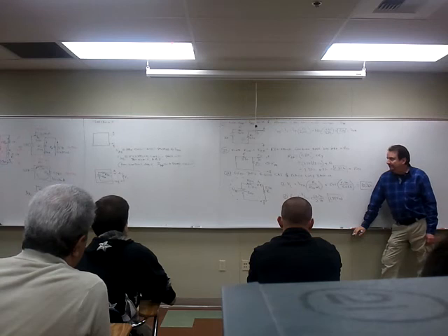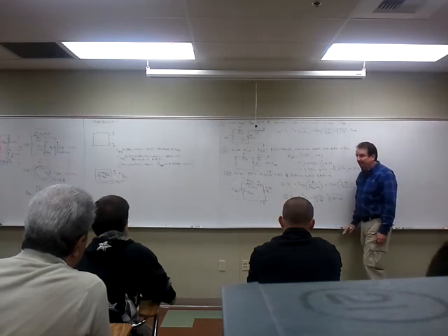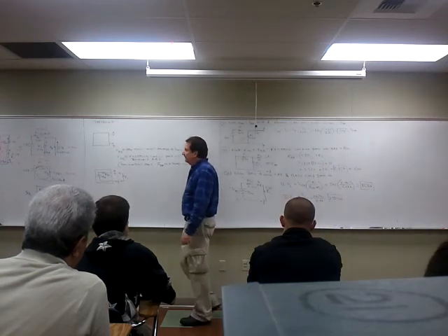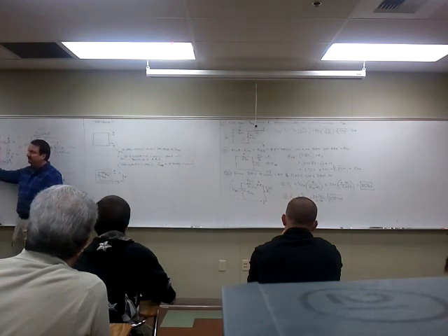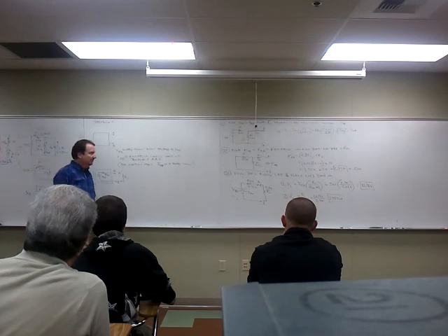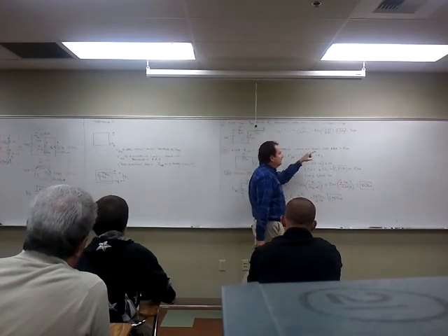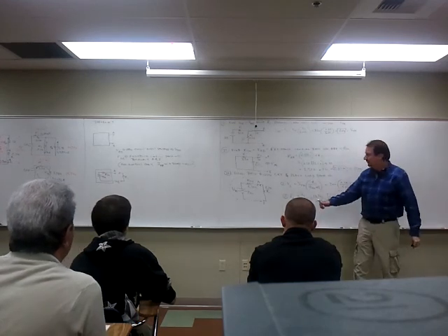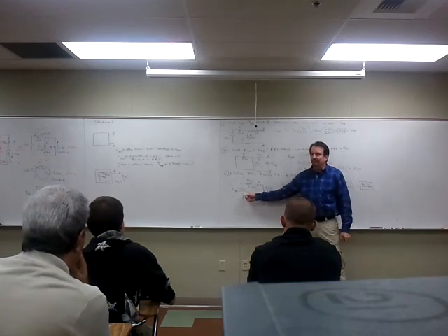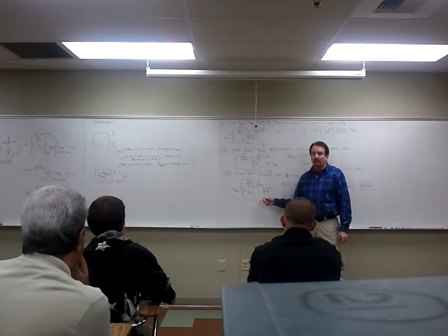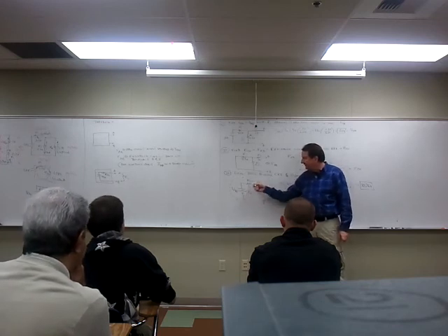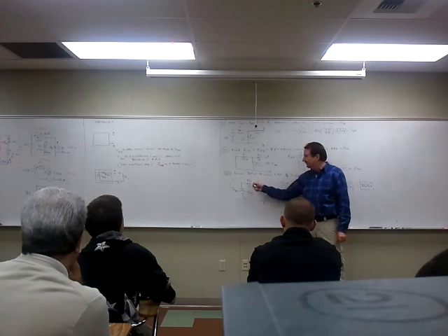That means, by the way, that whenever you find Thevenin, it doesn't have to be smaller than the original voltage in your circuit, because you're dividing it down someplace with some components there. So Thevenin is always going to be less than your starting voltage. So we got 20 volts. That 20 volts is what you label this voltage source in this equivalent circuit that always looks the same. It's always a voltage source and series resistor. The voltage source is labeled Thevenin. The series resistor is labeled Thevenin.